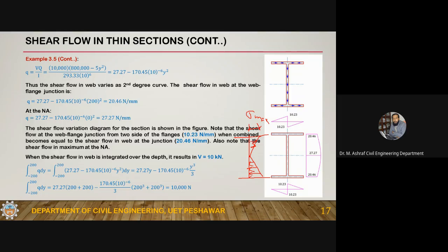Now in the case of shear, let's suppose I'm strengthening the web, which means increasing the thickness of the web. If I'm increasing the thickness of the web, I will get an increase in the resistance of the web. The stresses developed will be lesser if I increase the thickness. And this is a material which has some shear strength, and strength has nothing to do with the dimension.